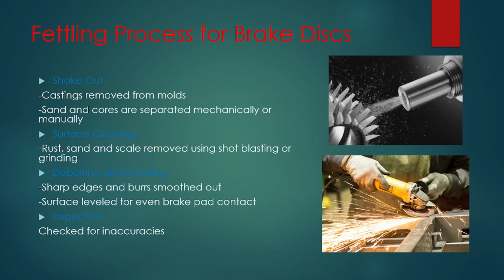So the fettling processes for brake disc. There are four of them: shakeout, surface cleaning, deburring and grinding, and inspection. For shakeout, casting is removed from the molds, and then sand and cores are separated mechanically or manually.